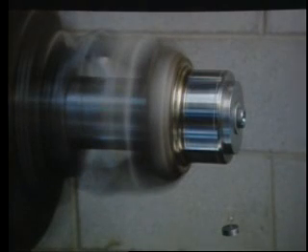This yoke is being checked for random grinding marks by chucking the yoke in a lathe with a 15-inch piece of cotton thread looped around the seal surface. A 50-gram weight is hung from the thread, and the seal surface is lubricated with 10W40 engine oil. As the yoke is spun at approximately 150 RPM, the thread should not move across the sealing surface of the yoke. If the thread does move, it indicates the microscopic grinding marks are not perpendicular to the yoke splines.